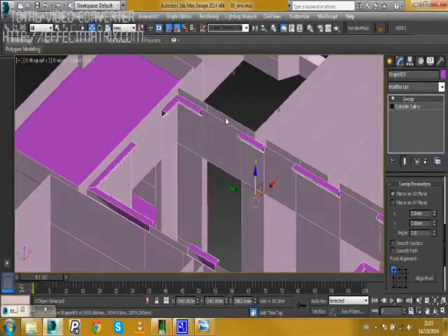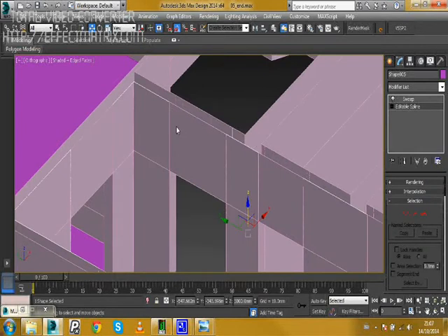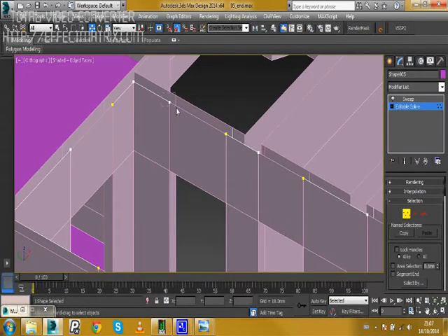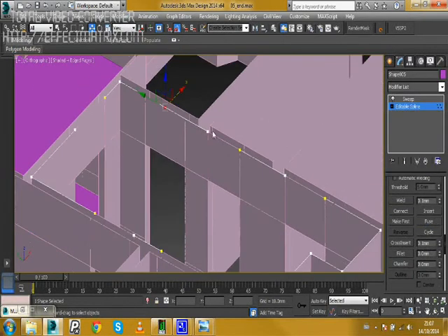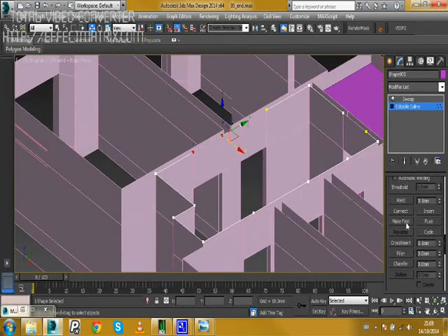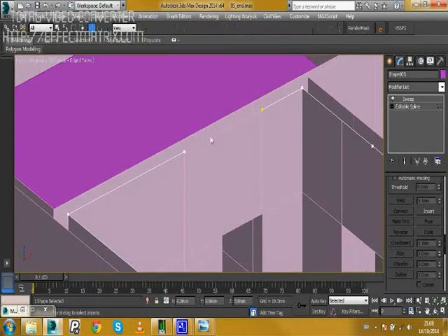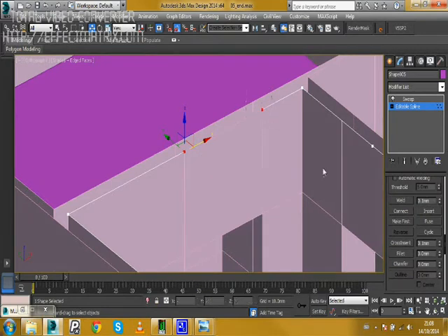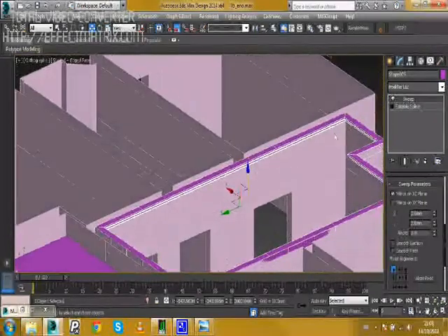That looks good. As you can see here, we'll just get gaps. So what we can do is go back to the edit spline. Just select your vertices. We'll just select these two, for example. We'll scroll down and we can just fuse these together. So we just do this with these. Like so. And we'll just select the sweep again. You can see that's sorted that problem out. I'll just fuse these last ones. Okay, so that looks good.